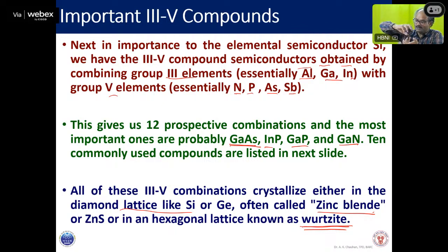Those 2, you can say this void, in place of the tetrahedral void, now it will become an octahedral void. So you have 3 spheres and then 3 spheres, and between them there is a void. This void is now an octahedral void, and you try to put a sphere inside that, and then eventually pull both the upper layer and lower layer apart because of putting a same size sphere.